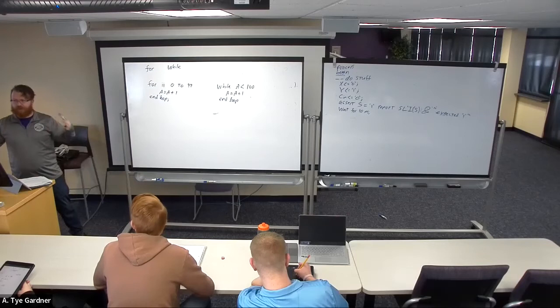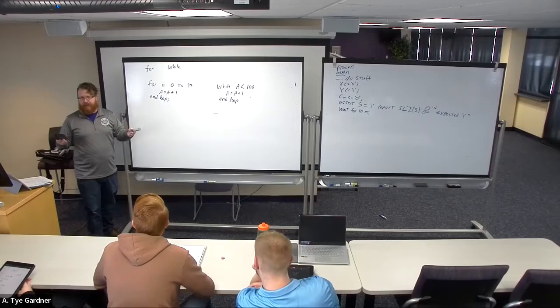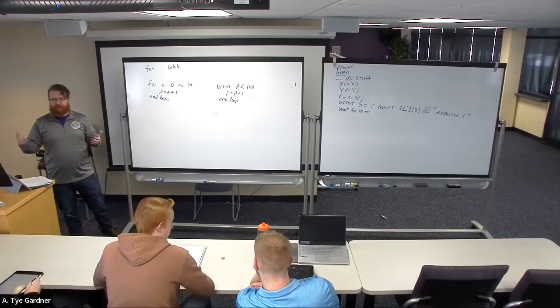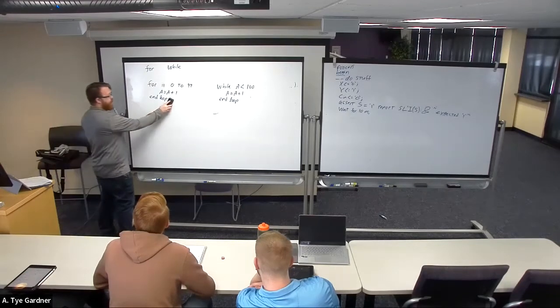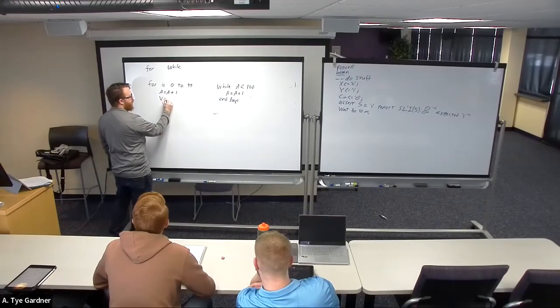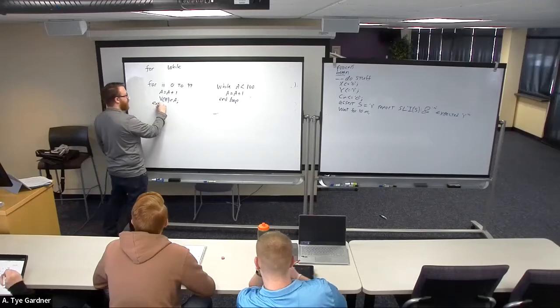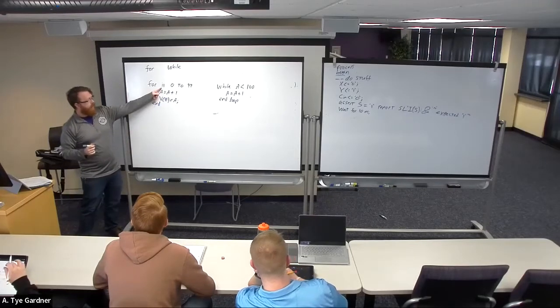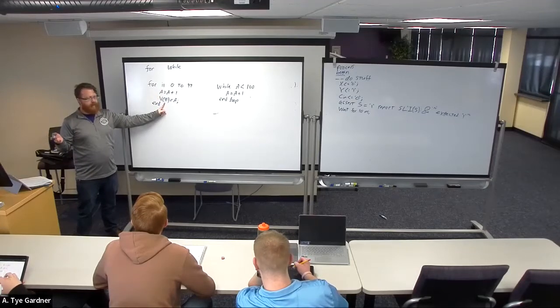Of course, there's much more to them. We can do lots of things. We can use I inside of this. So if we wanted to index something, so if I wanted to build a list of numbers, for example, so I had a huge standard logic vector that was 0 to 100, or sorry, 0 to 99, then I could say something like that vector at the index I is A. This I is going to increment up every single time that the loop runs. It will access the index of that vector and put A into it.